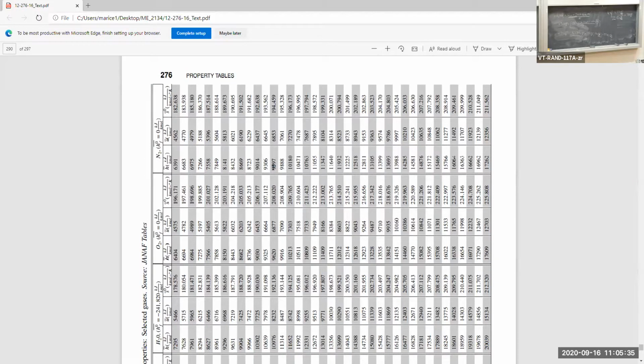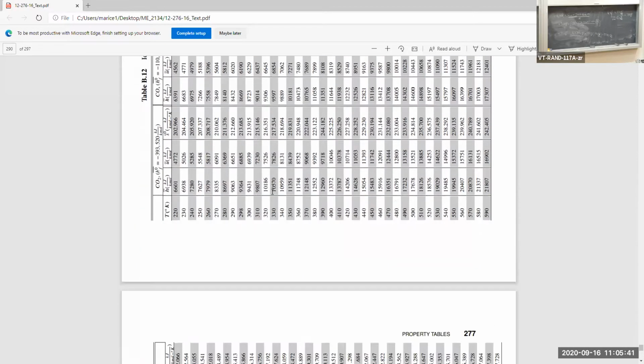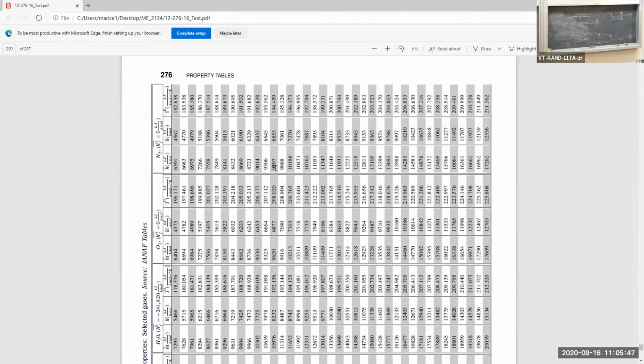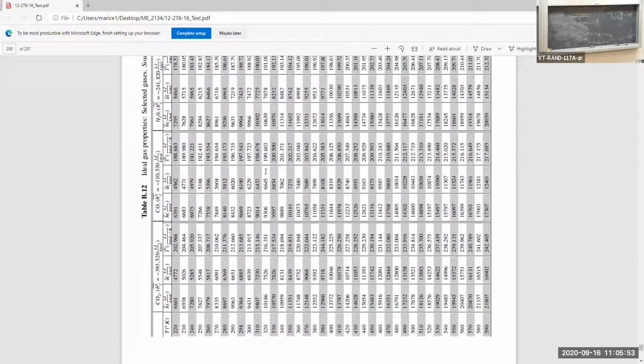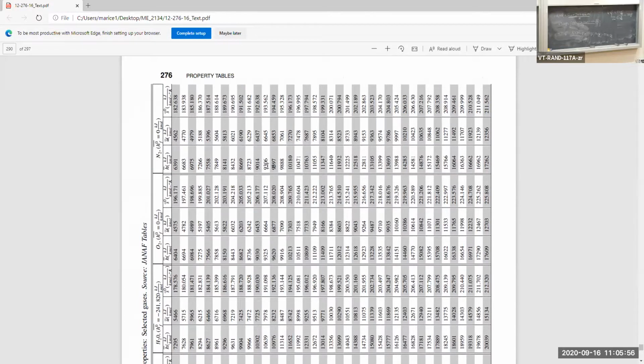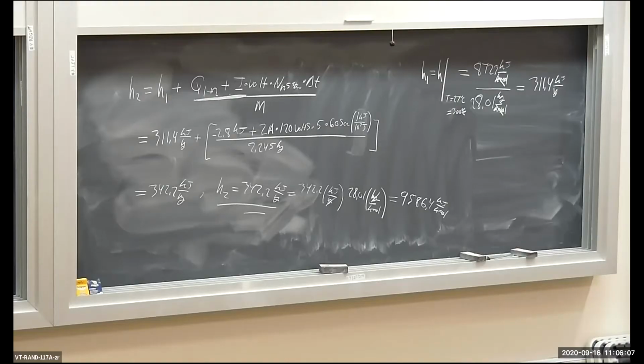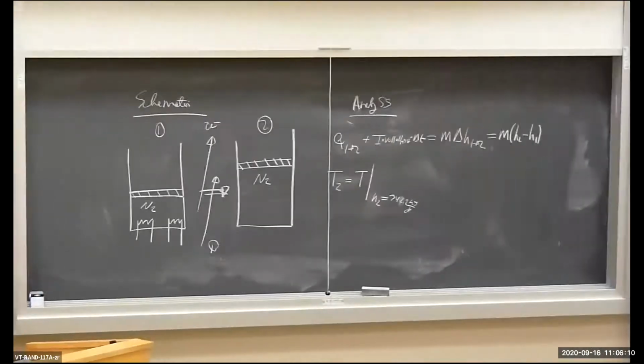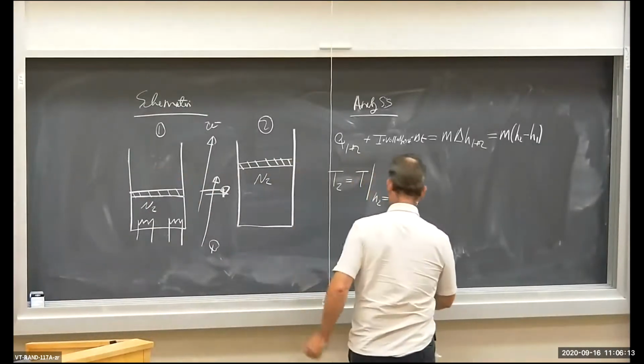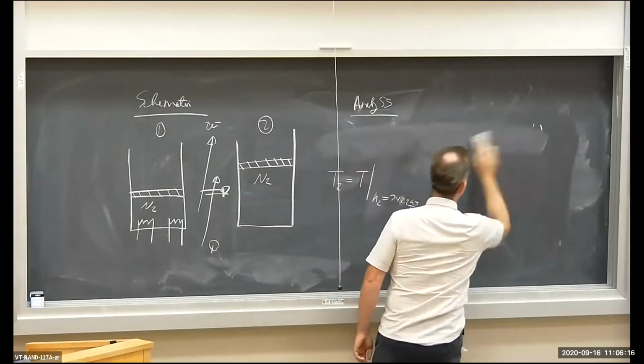So we're going to have to interpolate. Let's interpolate between these two enthalpies and therefore these two temperatures to find out the exact temperature. Specific enthalpy at 320 degrees Kelvin is 9306, and at 330 it is 9597. So let's do the interpolation right up here.